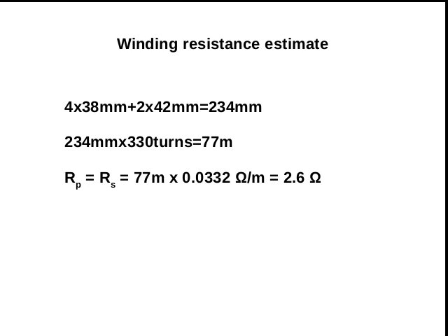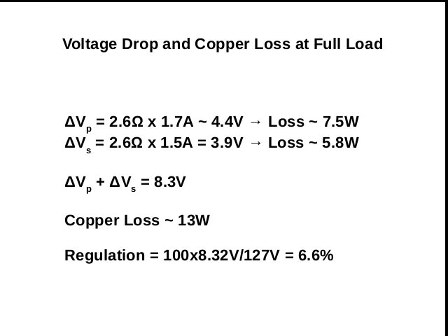On the primary, this will represent a 4.42 volt drop, and on the secondary an additional 3.9 volts, for a total of 8.32 volts at full load. This is approximately 6.6% of the nominal 127 volts, which is acceptable. We can directly sum the voltage drops because the turn ratio is 1:1. The general rule is that the voltage drop on the primary be divided by the turn ratio.